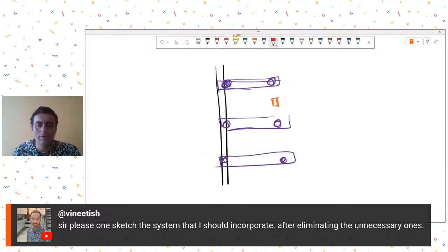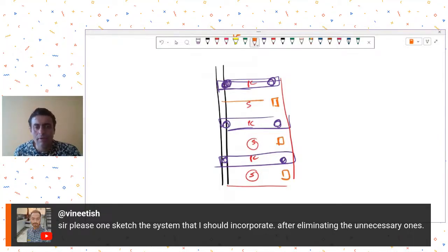So have your toe and heel slab. Now this will be a smaller slab, and this becomes my pile cap maybe. Now have your columns placed in between, maybe like this. Then have a tie arrangement. Try to make it stiffer. Stiffer means it should behave something like a counterfort.